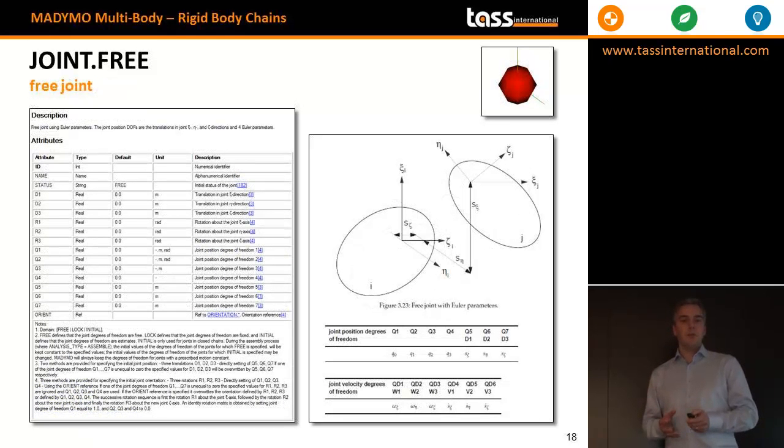Another example, the free joint, which is basically the opposite of the bracket joint. This is a joint with 6 degrees of freedom. As in a joint chain, every body must have a paired joint. But for instance, if you want a system that can move and rotate, translate without suppression with respect to reference space, it means that your root joint, your first joint in your chain, would be of the type joint.free. So it has 6 degrees of freedom, it can freely move in space.